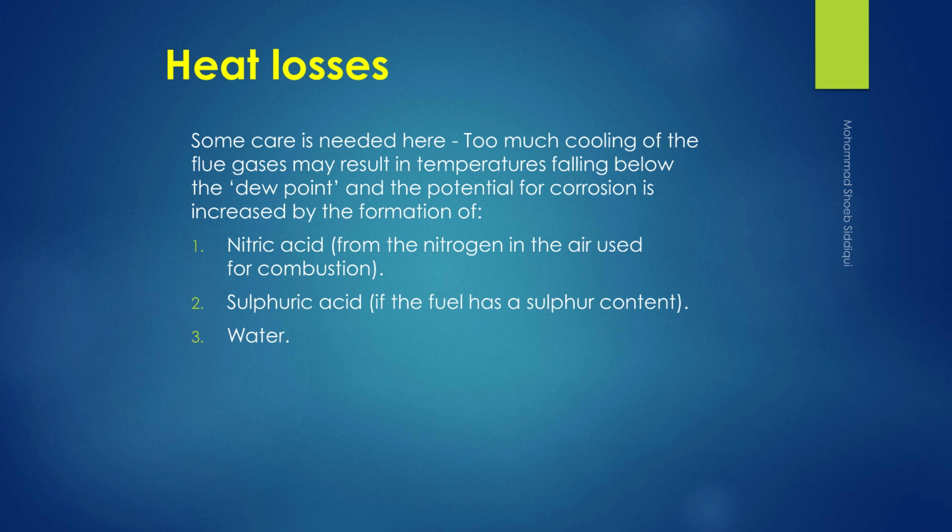Some care is needed here. Too much cooling of the flue gases may result in temperatures falling below the dew point, and the potential for corrosion is increased by the formation of: 1. Nitric acid from the nitrogen in the air used for combustion. 2. Sulfuric acid if the fuel has a sulfur content.